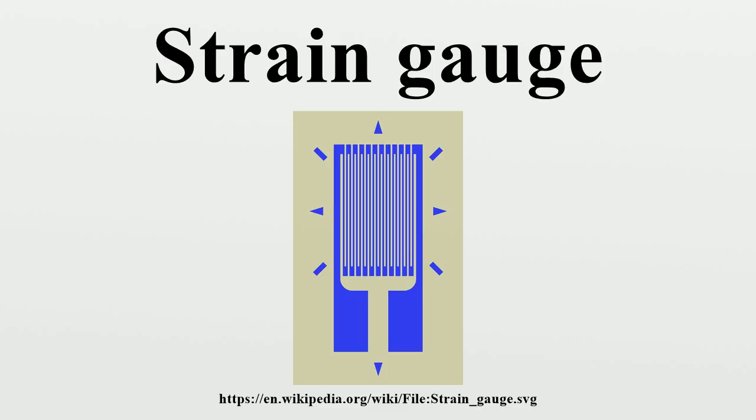Nanoparticle-based strain gauges emerge as a new promising technology. These resistive sensors, whose active area is made by an assembly of conductive nanoparticles, such as gold or carbon, combine a high gauge factor, a large deformation range and a small electrical consumption due to their high impedance.